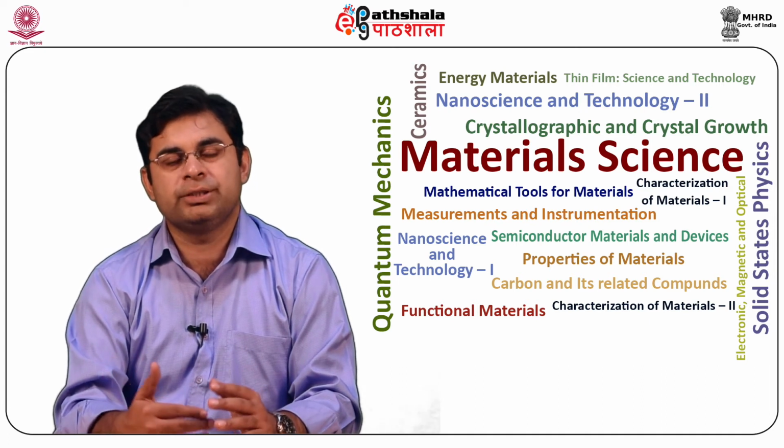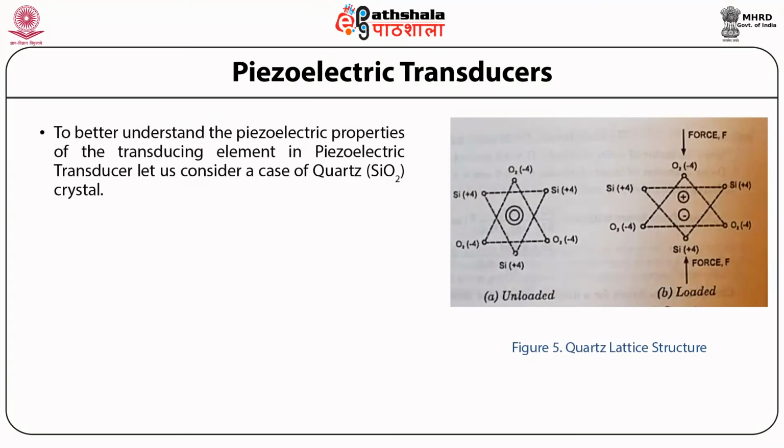external force or pressure. To better understand the piezoelectric properties of the transducing element in piezoelectric transducer, let us consider a case of quartz crystal. Figure 5 illustrates how opposing sides of the crystal get charged with application of external mechanical force.